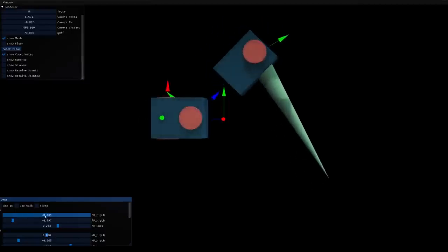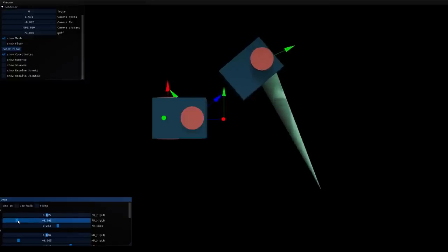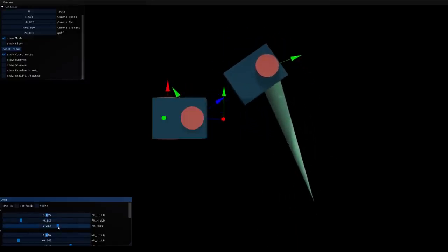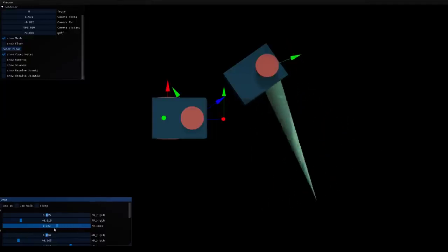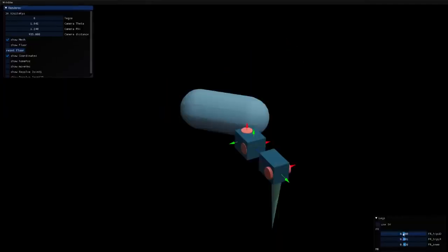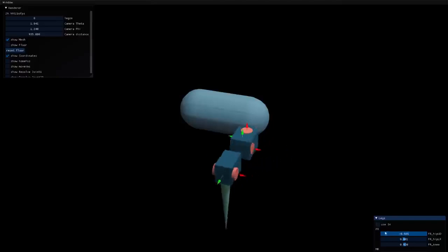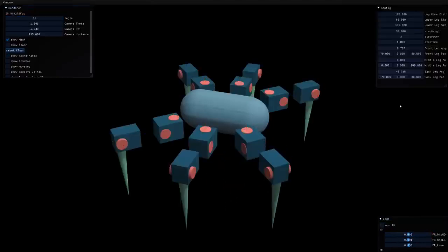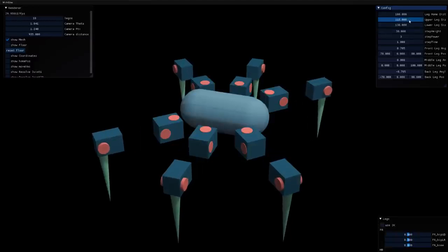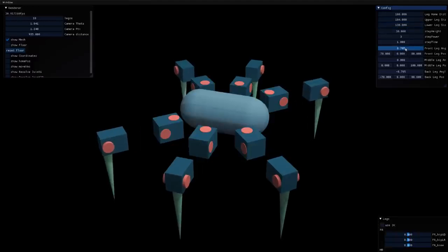a simulation. The only thing you can control with a real robot are the rotations of the motors. So I started to make a forward kinematics computer model that has that exact behavior. And with that, I could try to figure things out and start testing. Now, making a walking cycle with just adjusting the rotations of the motors is in theory possible, but that would be a very static and non-flexible thing. If I changed the length of a leg, I would need to start all over again.